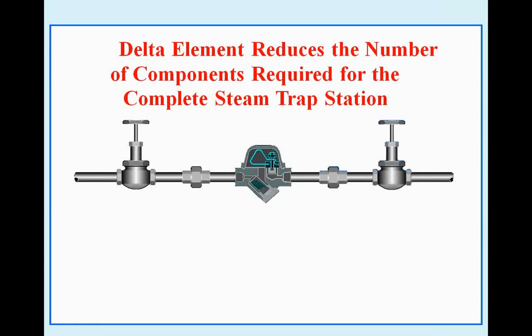And there's two broad points we want to make here. One, there is more than one component in a steam trap station, and that's worth mentioning, as we'll get calls that, hey, this trap keeps clogging. Well, do you have a strainer upstream? No, I don't. Well, there's maybe the cause of your issue.